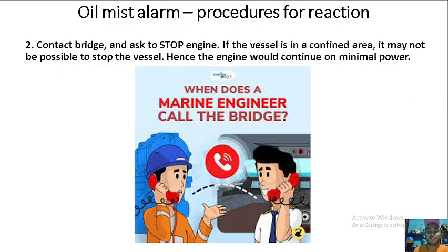Number 2 is contact the bridge and ask to stop the engine. The engineer should not stop the engine on their own because we don't know if there is traffic of vessels in the sea. If the vessel is in a confined area, it may not be possible to stop the vessel, hence the engine will continue on minimal power. The captain may change course so that they will go to a place in which they can stop the engine.